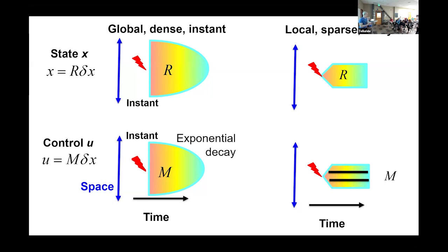But here's what you want to do. So here's the traditional problem with system identification: you never see open loop data unless you have a wind tunnel, right? If you just have a real system out there and it's not working very well and you're getting some data and you want to refine it, you don't get to take it offline. I mean, sometimes you do, but in this case you don't. So the point is, all your data is taken closed loop. So the best thing you can do is to estimate what these should be, okay?